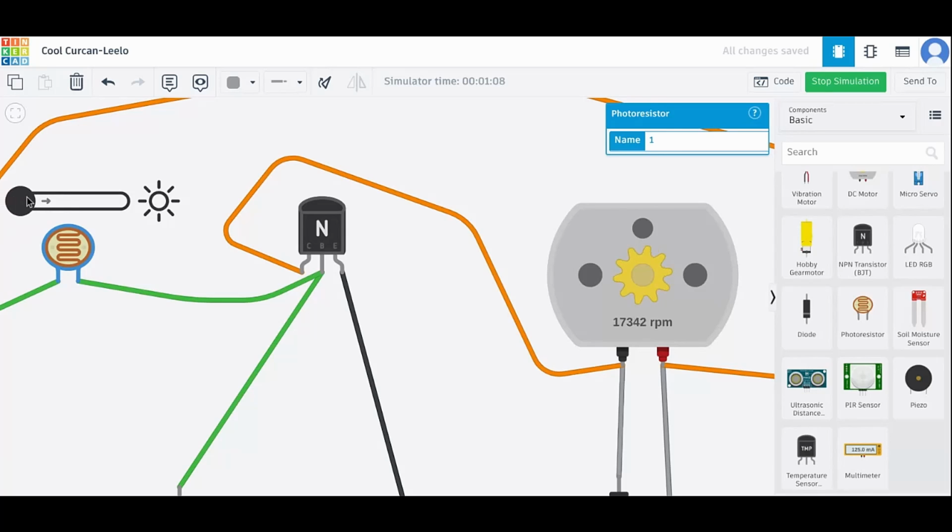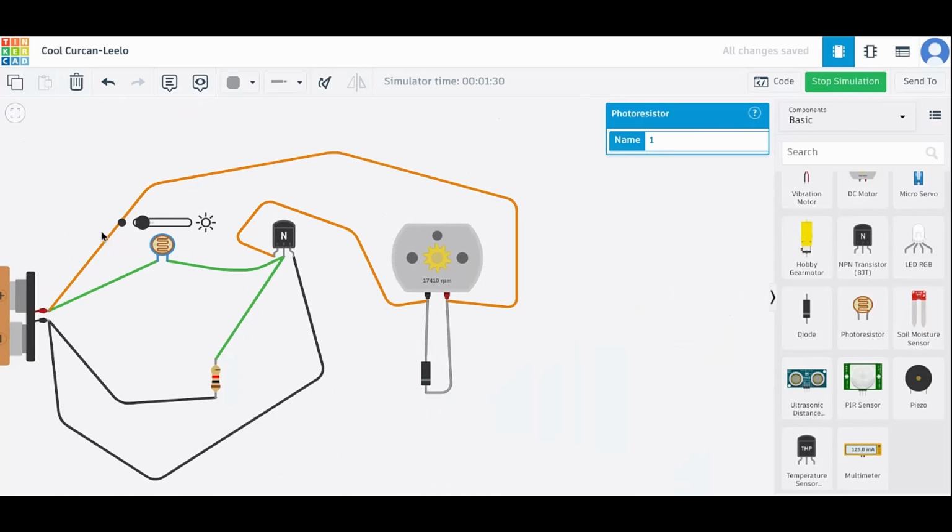To a make-believe extent, by turning the motor on and off, I'm controlling the speed of the motor. If you take the average motor, it's between 0 and 17,500 RPM. So if I do this sufficiently fast, I get roughly the average RPM. Does anyone know what I am trying to do? What was I trying to do? The name for what I just did.